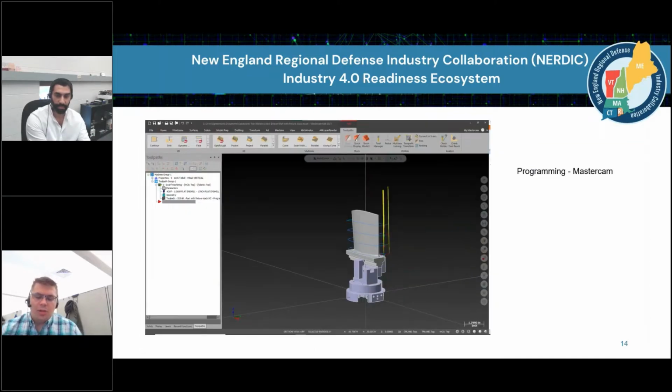In this case, our example is using a robot to selectively deburr a part and taking feedback from a scanner as to whether or not it's finished with the task of deburring. And then so it runs the deburring path, scans the part to check it for size. If the part is correct, it stops. If it's not correct, it steps in a little bit closer to the tool and runs the path again. This is a fairly complex task to program, and this is what industrial robots are particularly good at.